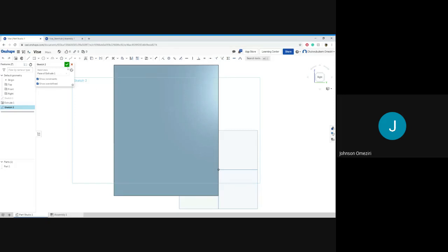So now we draw 2 corner rectangles. So we'll go to the rectangle tool. But this time, instead of selecting the center rectangle, select the corner rectangle. The corner rectangle is the one on the top, or you could just press the G key. So I selected the corner rectangle. So I'll start drawing. You see now, as I get closer to this edge, it changes to orange, and that icon appears beside it. So click from there, drag out. Again, it doesn't matter how it looks. We just want to get the rough shape out. Draw a second one. So we're drawing a cross here, a simple cross.